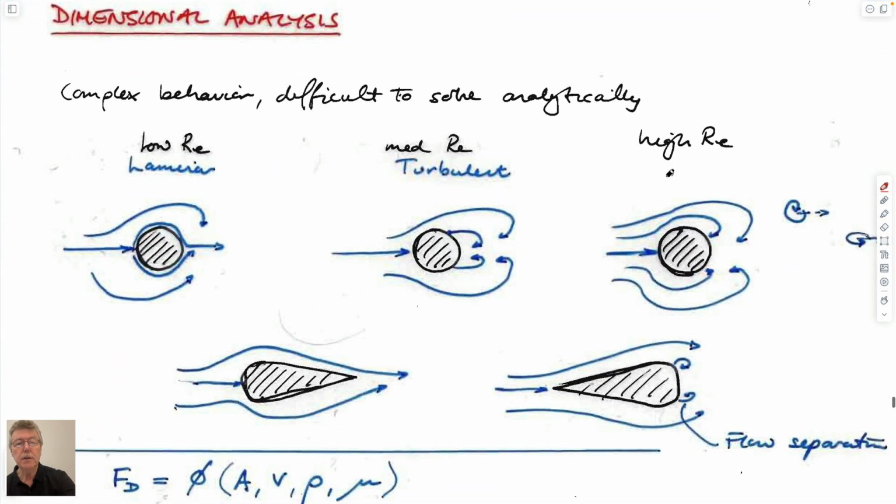And so we can go back to that kind of idea, and we would expect that as we go from low velocity flows, we have laminar flow where the flow hugs the cylinder, and therefore it exerts shear stresses on that cylinder, both top and bottom, always in the plane of the surface. And as the velocities increase, then the flow separates at the back, and we get these wakes forming.